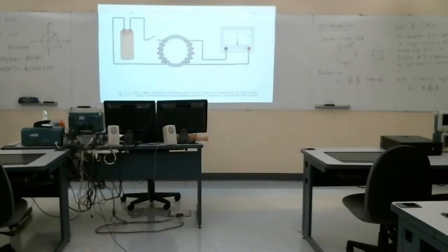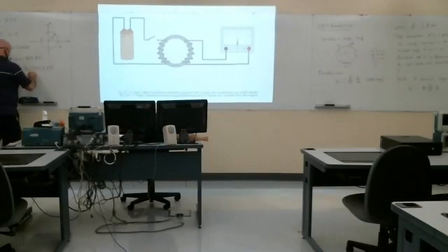So I was trying to be a little careful here about what portion is due to the changing B field. What portion of the flux is due to the changing B field? That's this portion. This would be the part that leads to transformer EMF. This portion would lead to motional EMF.